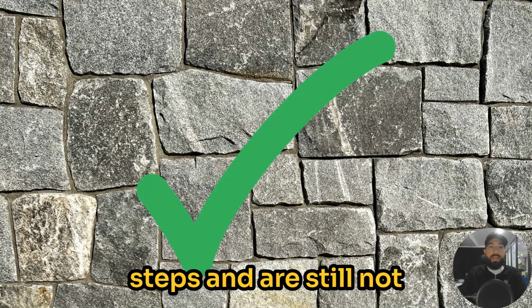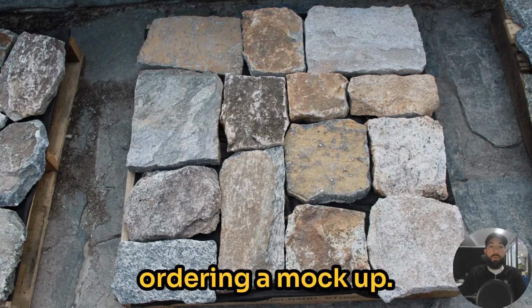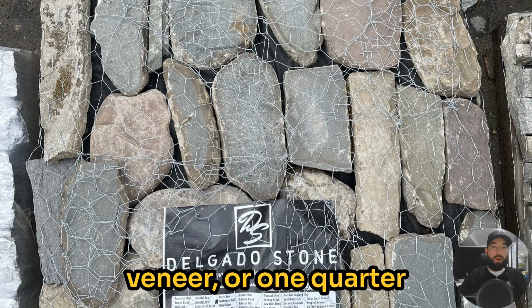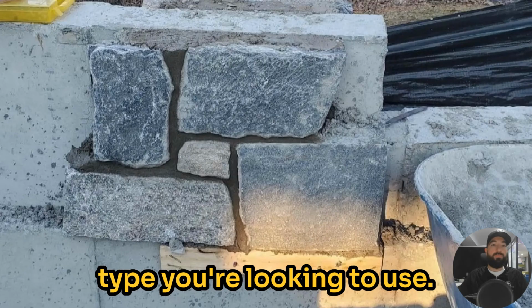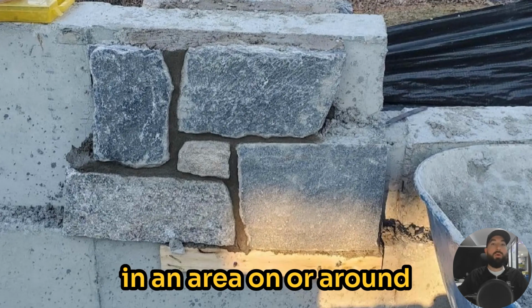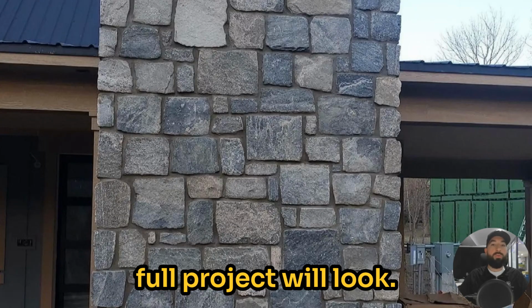If you've taken these steps and are still not 100% confident in your stone decision, we recommend ordering a mock-up. A mock-up will arrive on a pallet and either be 9 square feet of thin stone veneer or 1/4 ton of full bed veneer, depending on the veneer type you're looking to use. The goal of the mock-up is to confirm the stone choice you made. The mock-up will be installed by the mason in an area on or around the project site and give a more complete picture of how the full project will look.